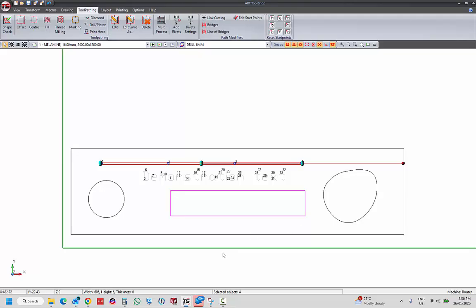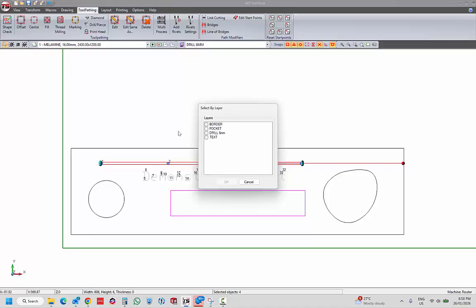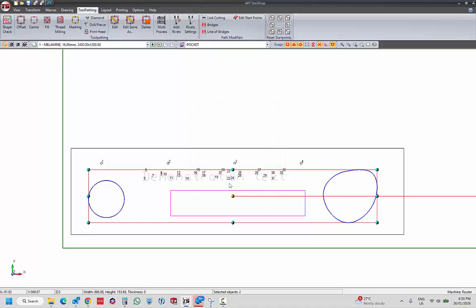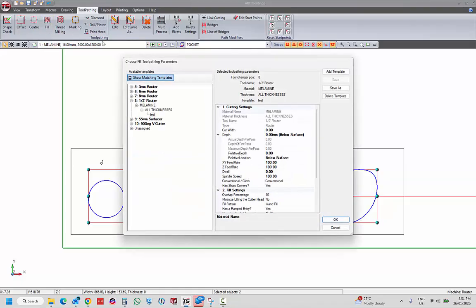This means I need to machine the whole area of the shapes down to a certain depth. I'll select it now. You can see that these two shapes are selected with the thicker blue line. Now, this layer doesn't specify, but it could have been named Pocket 5 millimeters deep, which would reduce any human errors. But for now, I'm relying on other documentation to know how deep. To add the Pocket tool path, I will use the Fill tool path here on the Toolpath menu. The Fill tool path has a few extra options, but it's quite logical.